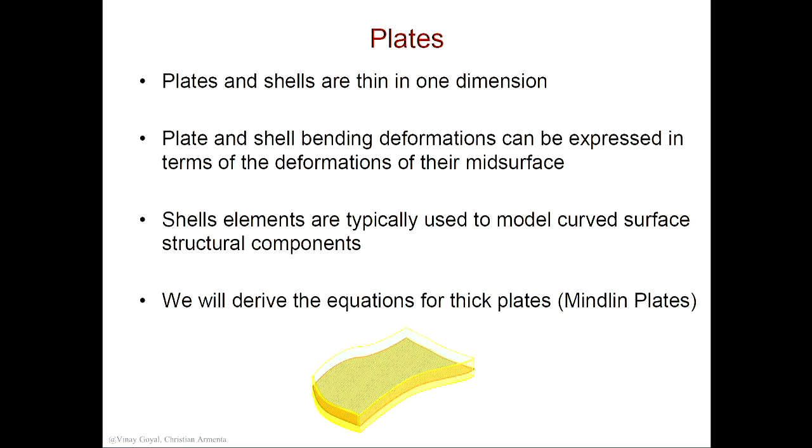For example, take a cylindrical pressure vessel. In that case, the wall could be thin, agreed? But the other lengths are long. The circumferential direction is long and the axial direction is long. That case can be modeled as a plate, or a shell, because only one dimension is thin. So using three-dimensional elements to model the thickness does not make any sense. You can just follow the deformation of the structure, following the mid-surface. In this theory, you follow the mid-surface in the deformation process. This is not very different from the Bernoulli beam or Timoshenko beam, where you have a neutral axis, and the deformation of the beam is represented by that neutral axis. In plates, the difference is that you have a mid-surface, and the deformation of that mid-surface tells you how the rest of the thickness is deforming and how everything else is deformed. Does that make sense?